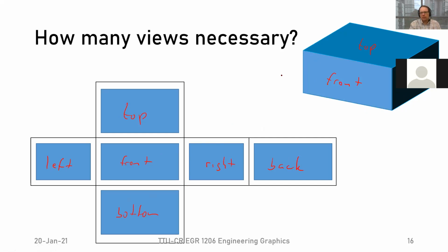Now, if we wanted to manufacture this block here, how many of these views do you think we actually would need to perfectly make this block? If there wasn't anything else, if it was all the same color and the same finish. Three views. Yeah, the height, the length, and the width. We would need those three things. That's correct. But now the question is, do we need three views to give us that? No. So maybe two. Only top and front, we can get away with that, right?